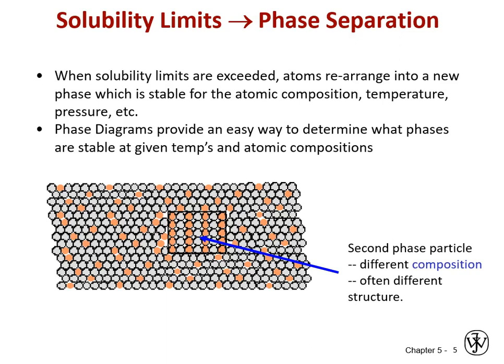And this picture shows an example of that for a solid solution of, say, maybe copper and aluminum. If you imagine the orange circles being copper atoms and the gray circles being aluminum atoms, after a certain concentration of copper has been introduced, you have so much, the material reaches a point where it can dramatically reduce its energy if those copper and aluminum atoms rearrange to one little volume where they're in a 1-to-1 ratio. And that little phase is known as an intermetallic or a stoichiometric compound.